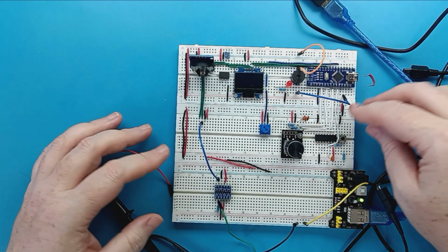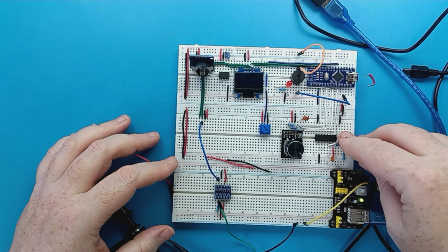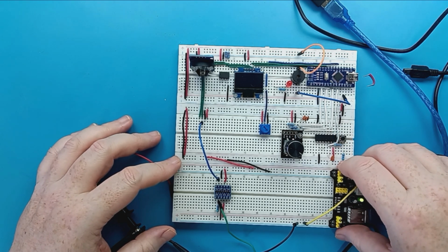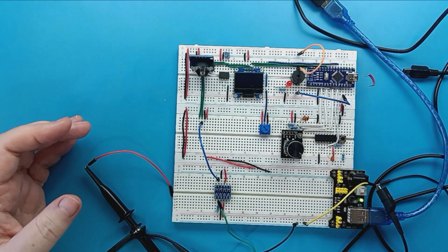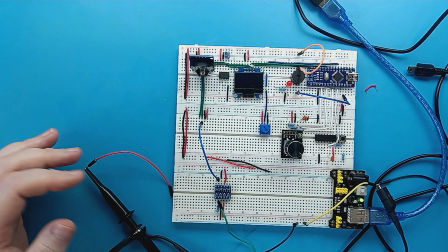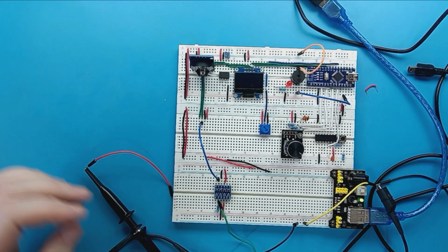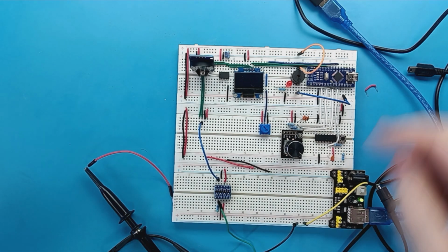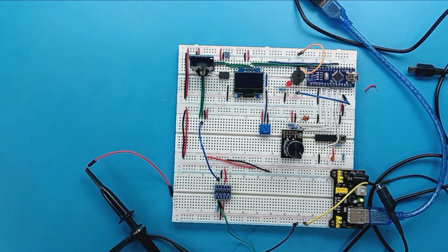Oh, okay. Okay, I know what I've done wrong. I've disconnected the 5 volt supply from the Arduino. Originally the 5 volts was coming through the USB. I'm now not using that. I'm using this 5 volt rail. So obviously the Arduino powered off because it didn't have any power.